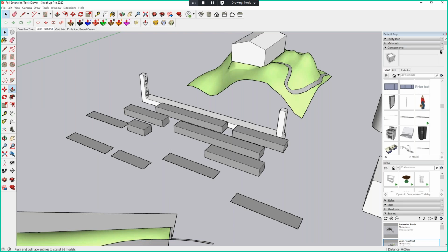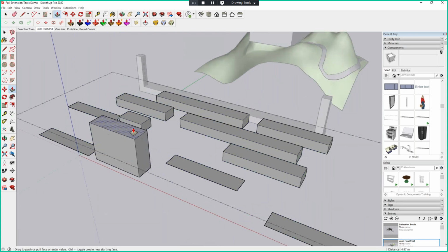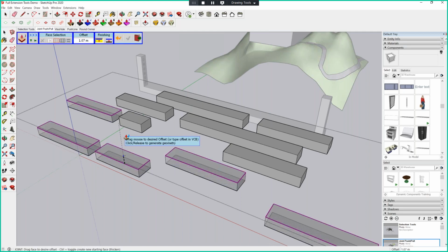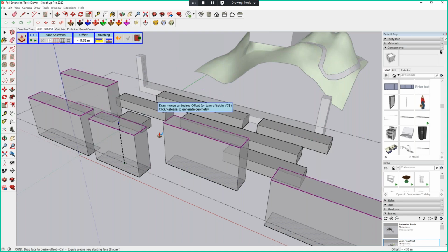If you use your push-pull on flat surfaces, like this one that we have here, you realize that, yep, you can do your push-pull on these models. But it is not allowed to do a joint push-pull of multiple surfaces at once. You can't do that in your native tool. So the J icon here will allow you to do a joint push-pull. What you have to do is pre-select the faces that you want to push-pull. Click J, which is the blue color icon, and you can bring it up a certain distance. So this allows you to join push-pull multiple surfaces in one go.